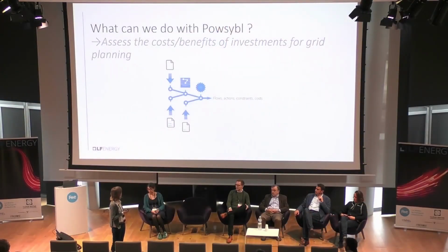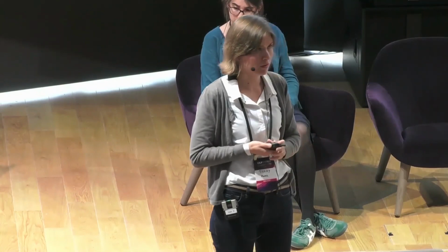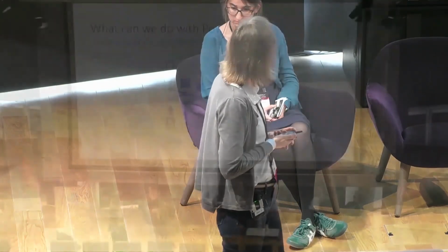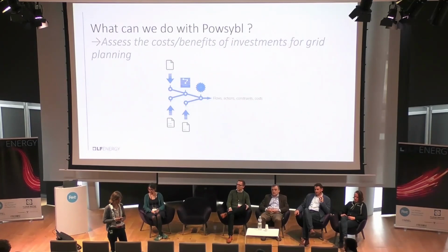And we are doing what we call a mapping. A mapping is, for example, you can map to a generator several scenarios to explain what could happen in the future. And after that, we use what we call an optimal power flow to say what we have to do to reinforce our network.